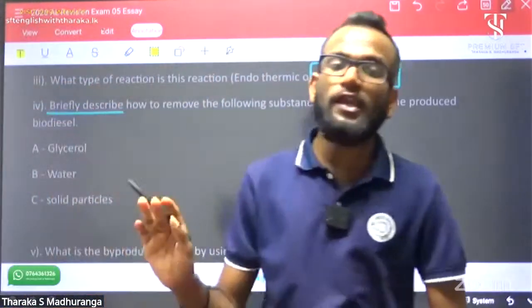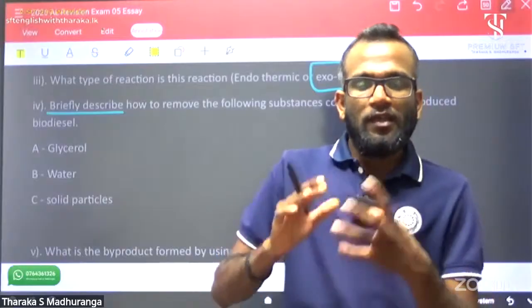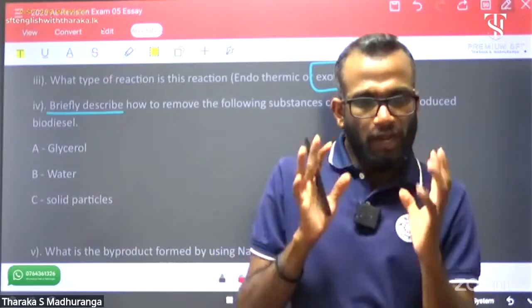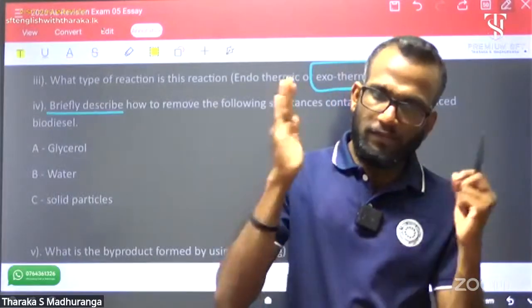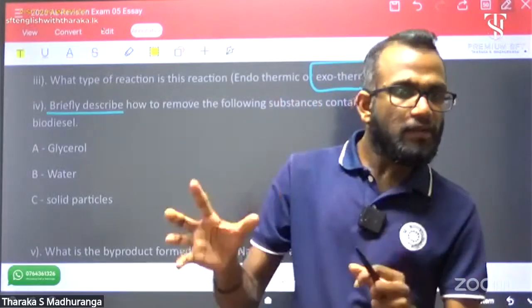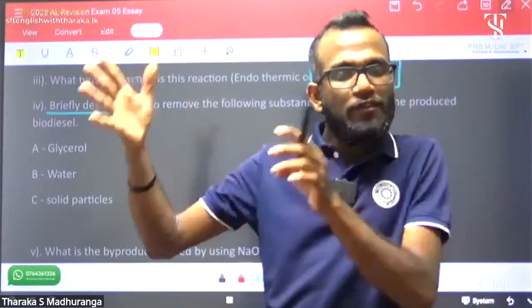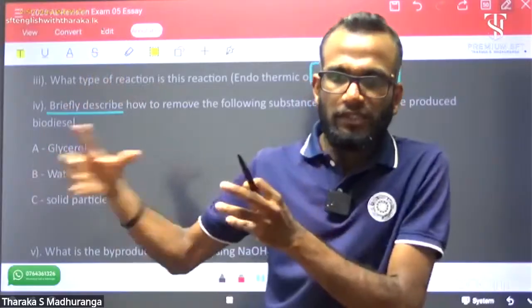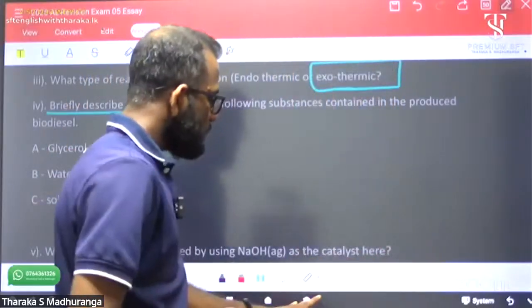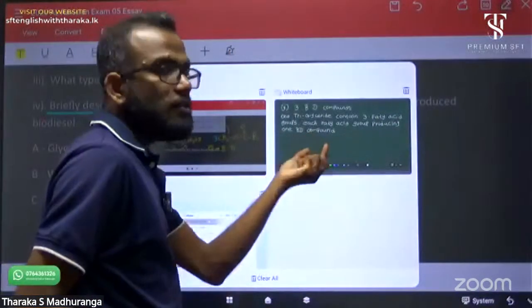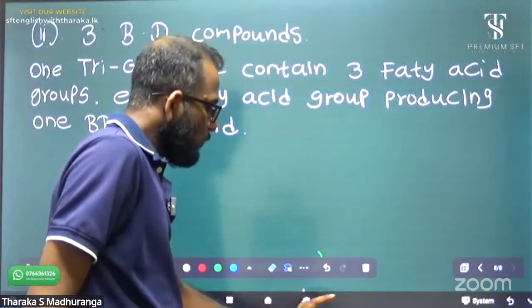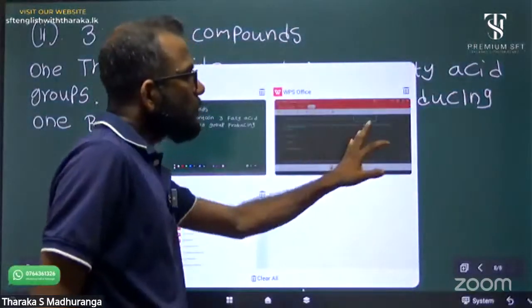Okay, I separately explained the biodiesel production. Biodiesel production actually means trans-esterification. In trans-esterification, what are the raw materials? Triglyceride and methanol. As a result of this trans-esterification reaction, it produces glycerol and biodiesel. Additionally, it produces soap. That's the main problem, right? Okay, that's the story.